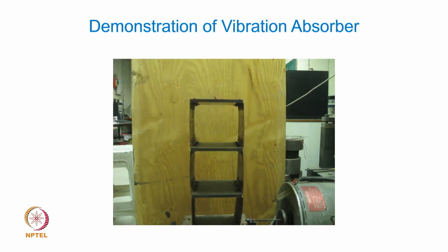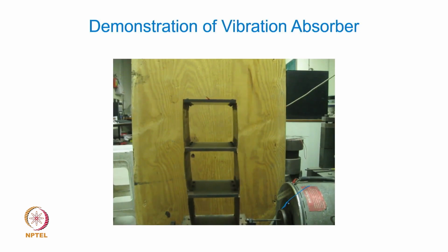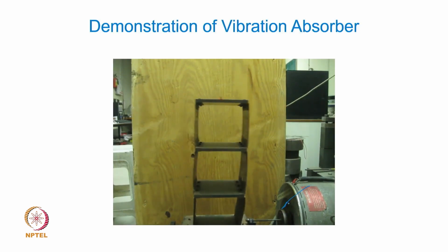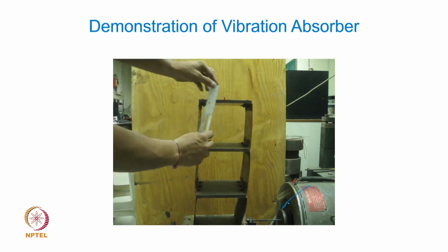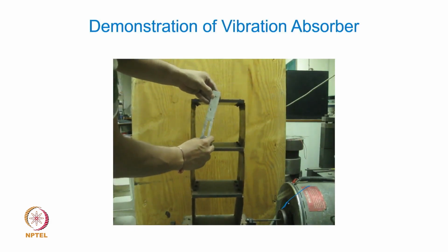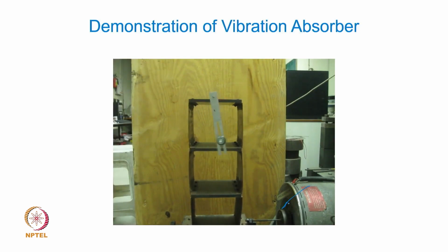By removing this, you can see very clearly how the shaker is shaking the base. It's just like an earthquake moving the base or foundation of the building, and you can see this entire multi-degree of freedom system is rocking with large amplitudes of vibration. The first fundamental mode is very clearly seen. All the masses, or all the floors, are moving in the same phase, and now I just put this pendulum, see this pendulum start swinging, and the parent system amplitude is quite close to 0.